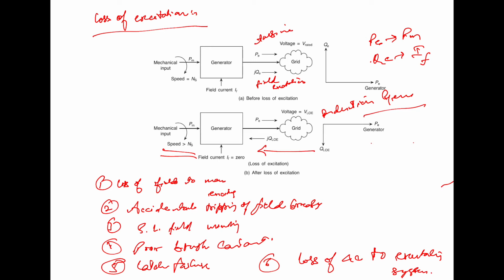Operation as an induction generator necessitates a flow of slip frequency current in the rotor, the current flowing in the damper windings, and also in the slot wedges and the surface of the solid rotor body.